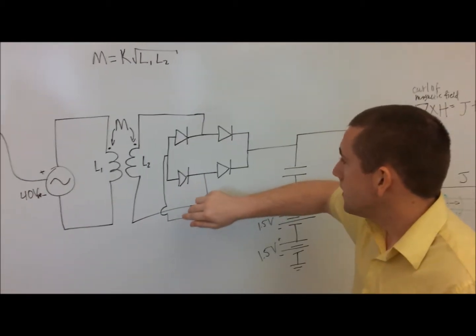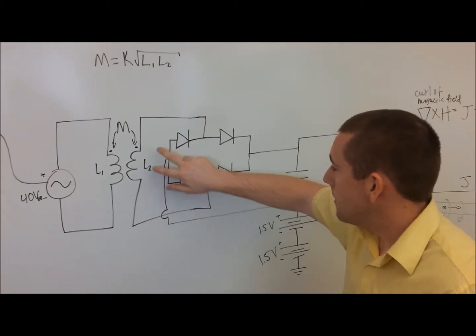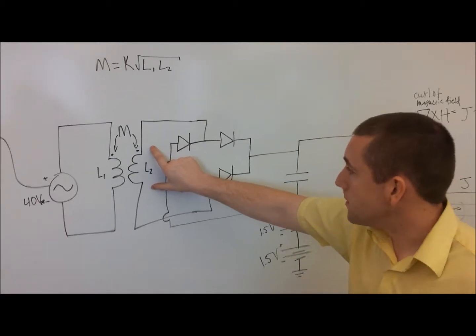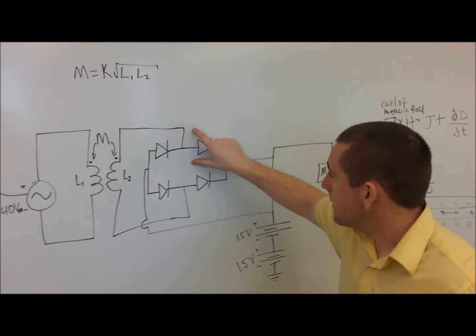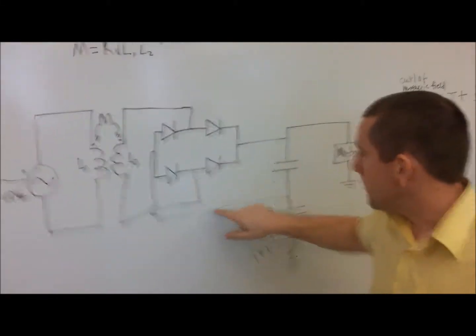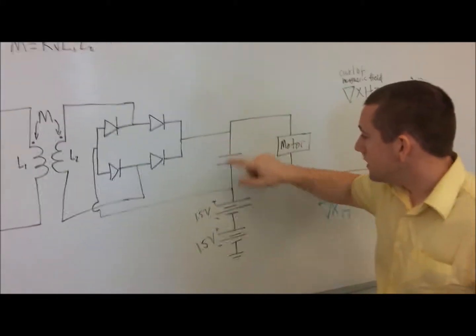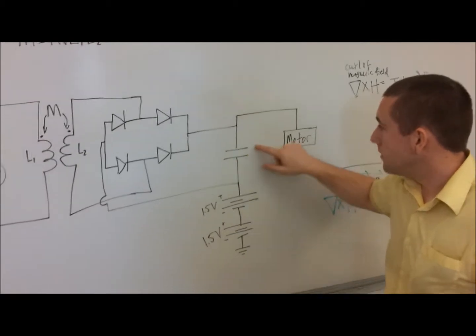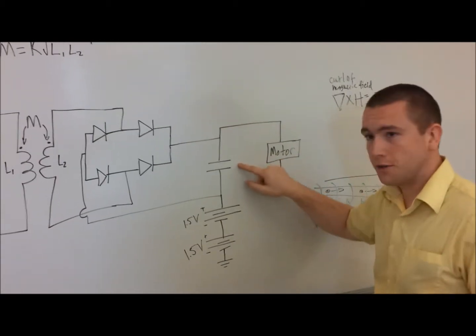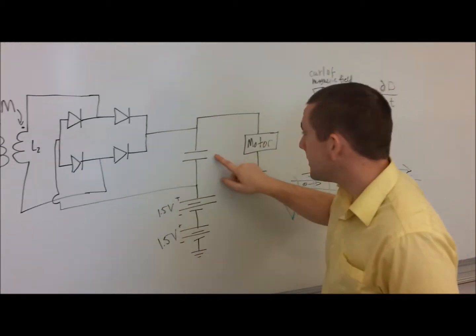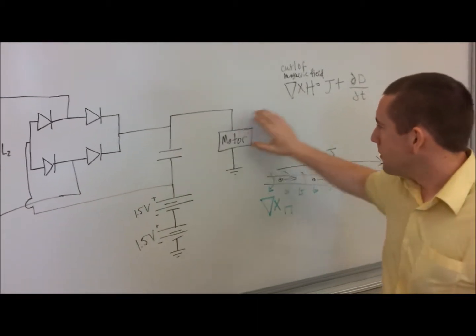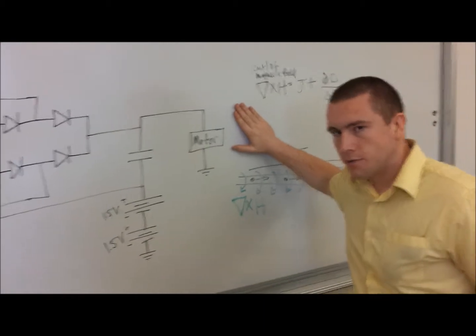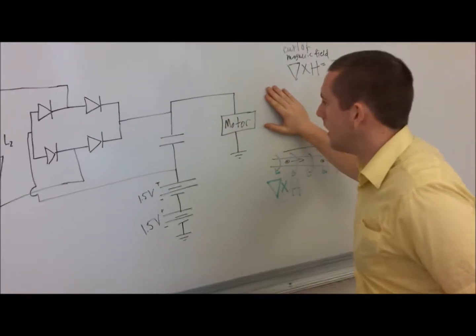We took the AC signal that we got from these coupled coils to a rectifier. Then we got a DC voltage out of that using this capacitor. We actually used a 1 farad supercapacitor there. And this car was designed to run off of 6 volts.